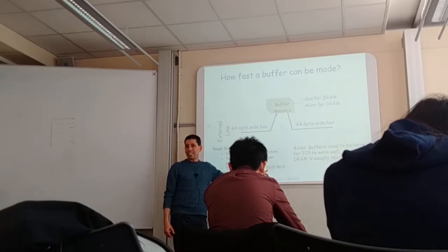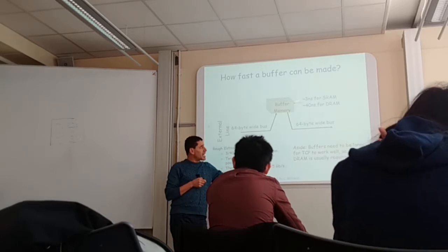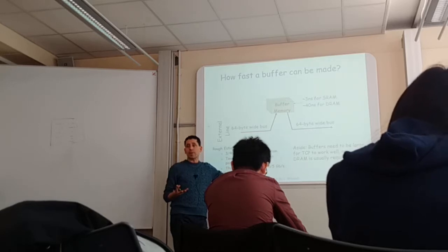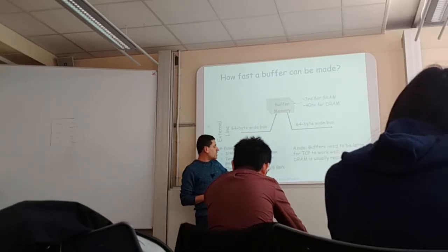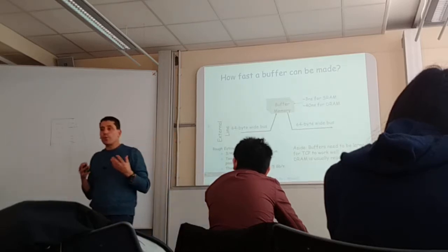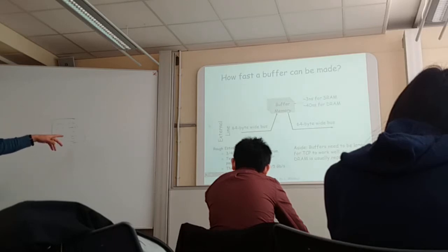In order for this memory to absorb 64 byte packets at this access speed, and each 64 byte packet must be absorbed twice, 2 operations on each packet, you will need this memory to have a bandwidth of 80 gigabit per second. It should process at the speed of 80 gigabit per second. Is it clear what's said there? Somewhat making sense?